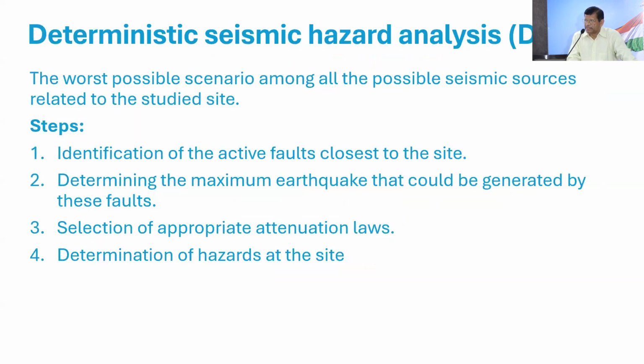What is deterministic? I always prefer the deterministic, because the deterministic is the important thing. I will show you the definition: the worst possible scenario among all possible seismic sources related to the study site.